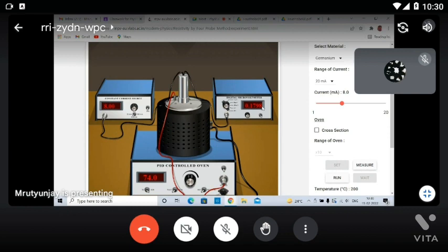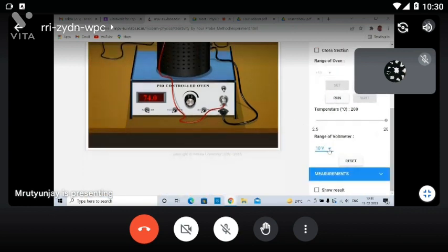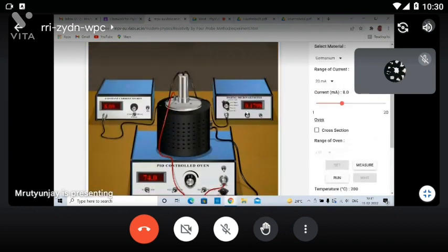Anyone can reply? So we are getting it in volt or in 10 volts? This is in volt. Actually this is the maximum. Suppose we selected 200, that is the maximum one. That means selecting 10 volt means the multimeter can show observations up to 10 volt. More than 10 volt, we will not get anything. It will show 0. Got it? That's the maximum limit. But this is in volt only. Clear?